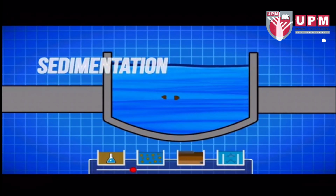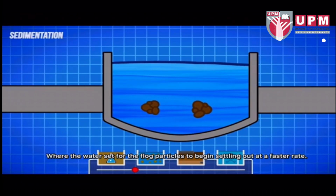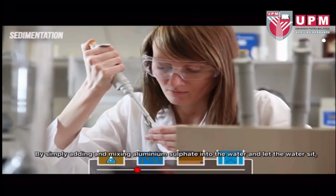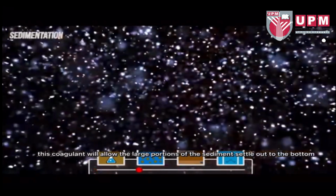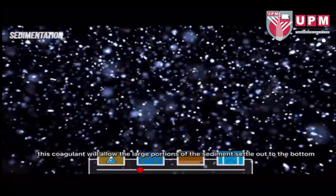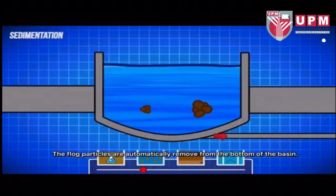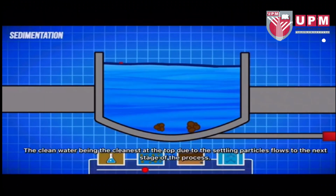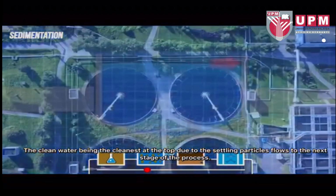In the sedimentation tank, the water is set for the flock particles to begin settling out at a faster rate. By simply adding and mixing aluminum sulfate into the water and letting the water sit, this coagulant will allow a large portion of the sediment to settle out to the bottom as sludge, which can be taken away to a landfill. The flock particles are automatically removed from the bottom of the basin, the clean water being the cleanest at the top, and flows to the next stage of the process.